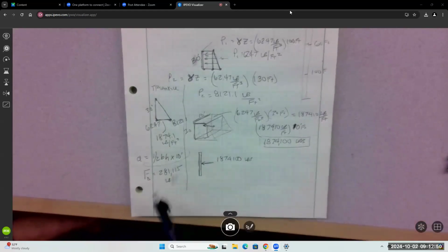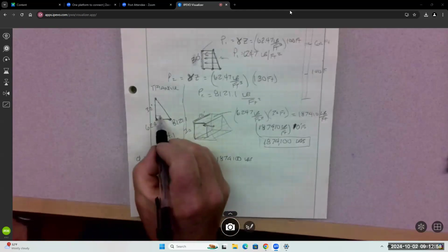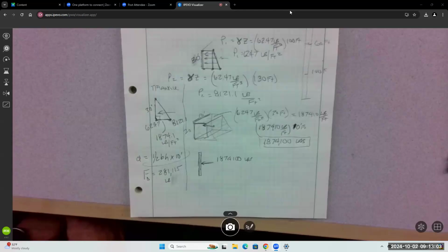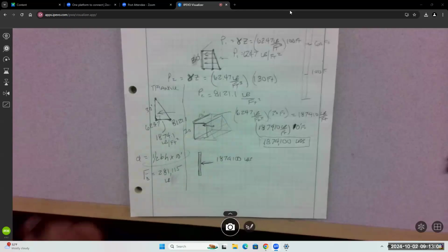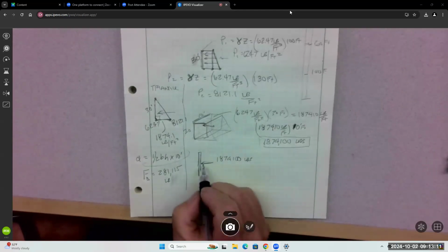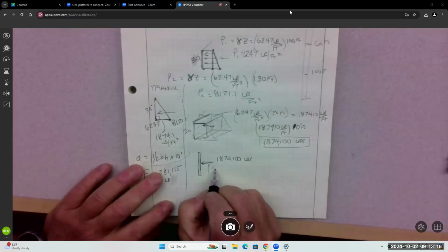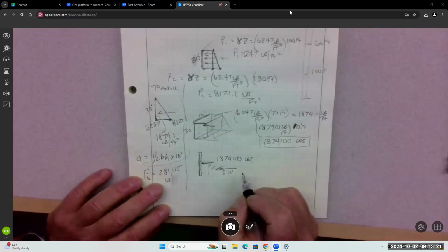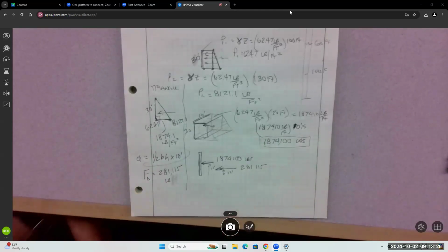And where's that at? Correct, it's 1/3 from the 90-degree. So from right here, this gets concentrated 1/3 the height, or 2/3 from the pointy end. And since we're at 30 feet, that's a pretty easy one to do. This one's at 15, right? And the triangle is at 10. 281,115.